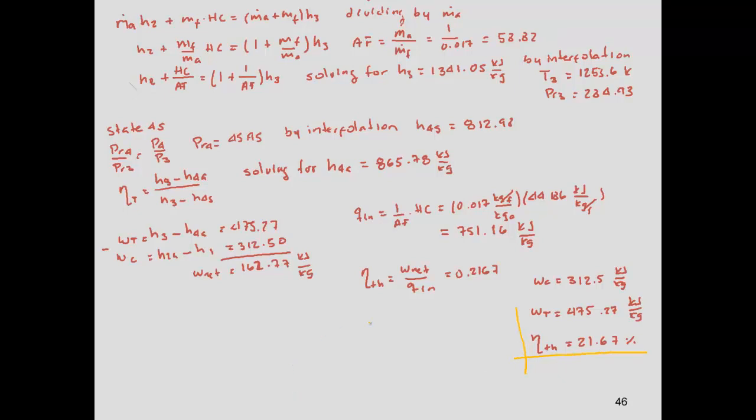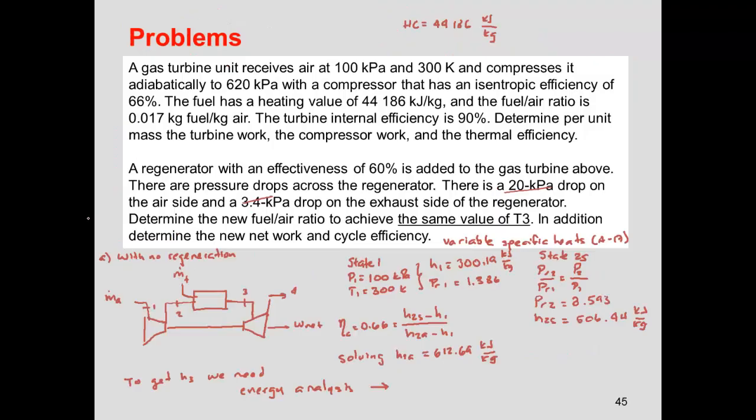And next we are going to do it with the modified cycle, with regenerator. In this case, we're going to modify this scheme and add the regenerator here.